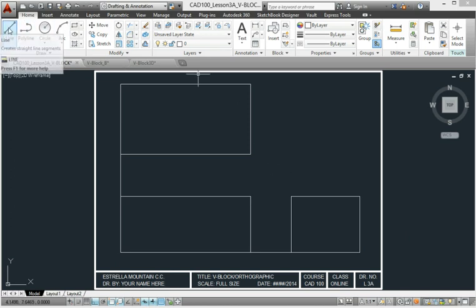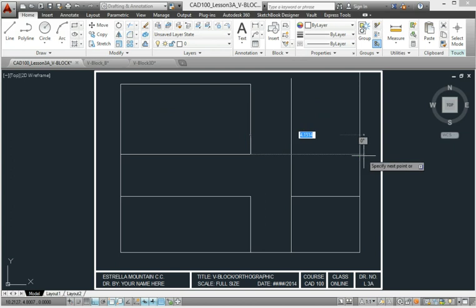We're going to need a new type of box up here. It is called a projection box. Sometimes it's called a miter box because it includes what is called a miter line. A miter line is a 45-degree angle line. Here, this is the miter line. It is created using the depth of the block from the top and the right side views. This miter line helps us transfer information from the top view to the right view or from the right view to the top view. We're going to be using that for this drawing.